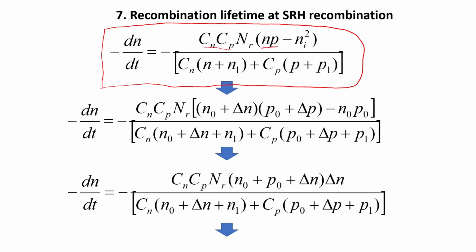Here we have the product of total concentrations, so it is actually equilibrium plus non-equilibrium charge carriers, and the intrinsic charge carrier concentration in second power. Also in the denominator, what is important, we have these guys N1 and P1, whose physical meaning is equilibrium charge carrier concentration.